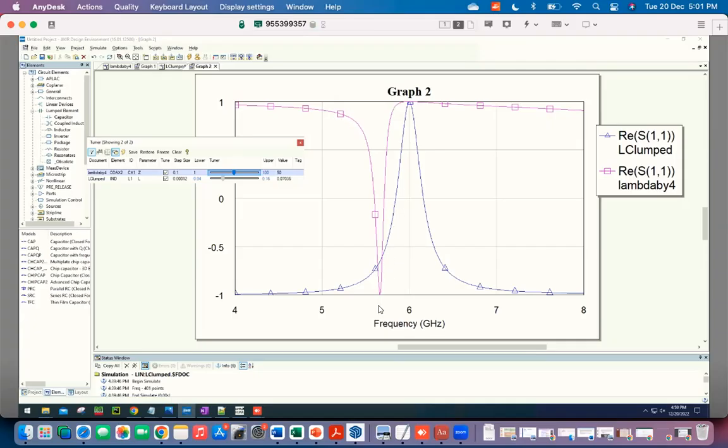But it doesn't matter as long as you're slow. In fact, the reason this asymmetry is so pronounced is that the capacitance value is actually still too high for a typical situation you would encounter, because this line width is still too much. It's like this is 5.598 to 5.712, so that's like 114 megahertz.